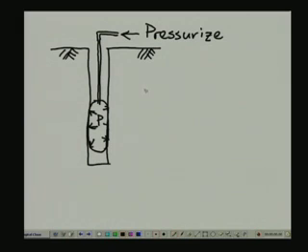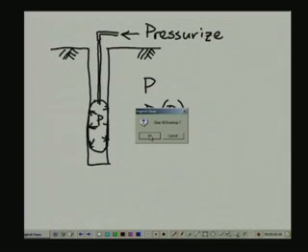So we keep track of both pressure and the diameter of the borehole, which is going to be a function of the pressure. Now interpreting these data, we can find out the in situ state of stress as well as other deformation characteristics of the rock around the borehole.